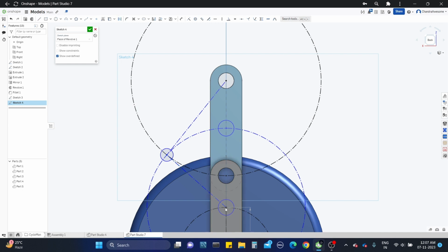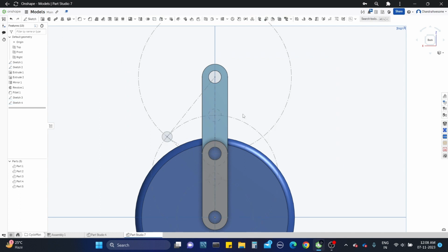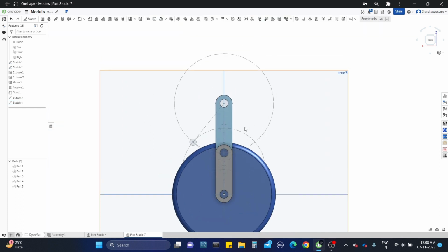and join like this. Now by using the dimension tool, we can clearly understand how much angle it should be each. It is 38.65 degrees and 48.509 degrees. Okay, let's switch. Now let's check whether it is right or not in the part itself by using the transform.